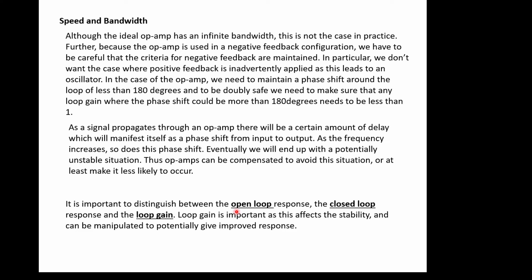So ideal op amps have infinite bandwidth. Obviously in the real world we don't have that, and we will have seen earlier that op amps start to actually fall away at a few tens of hertz in terms of their frequency response. We also have to worry about negative feedback, because they need to be operated in negative feedback mode, and we'll talk about negative feedback shortly. So we have to make sure that the criteria for negative feedback stability is maintained. So we don't want positive feedback, probably not, because that turns these things into oscillators, and we'll talk about that a bit later on in the course as well.